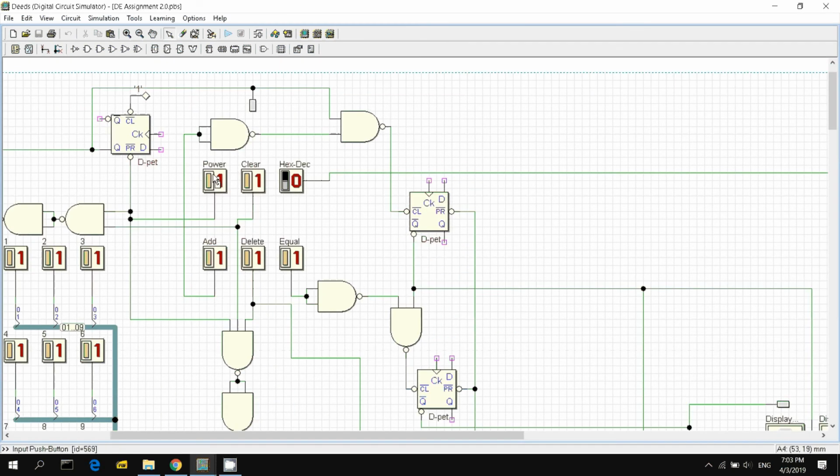So this power connects to this D latch, the preset. Which means that when this power turns to 0, then this Q will become 1. Originally, before you do anything, this Q has no defined state. It's neither 1 nor 0, it's in an undefined state.